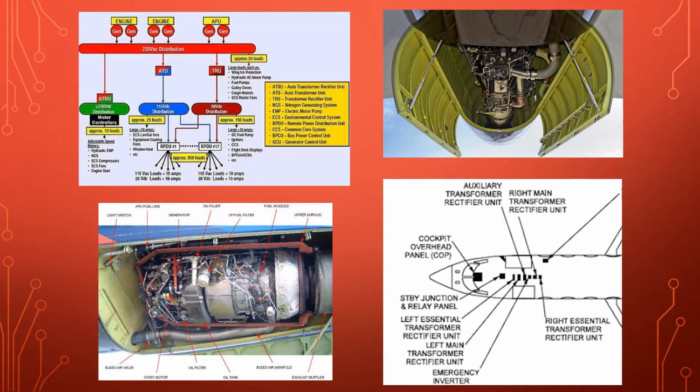More sophisticated electrical systems are multiple voltage systems using a combination of AC and DC buses to power various aircraft components. Primary power generation is normally AC, with one or more transformer rectifier units providing conversion to DC voltage to power the DC buses. Secondary AC generation from an APU is usually provided for use on the ground when engines are not running and for airborne use in the event of component failure.